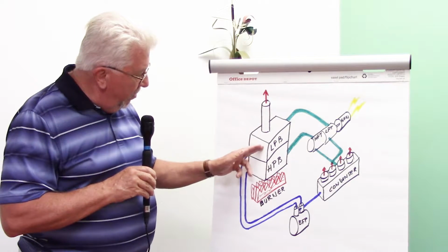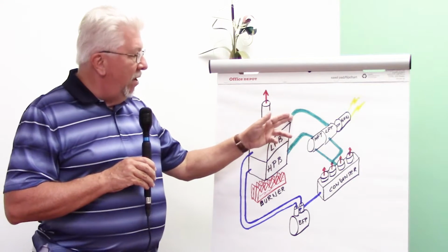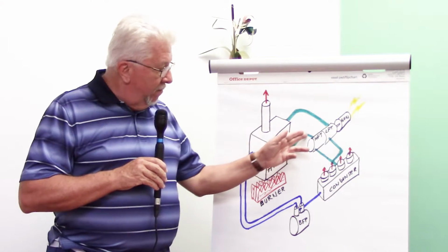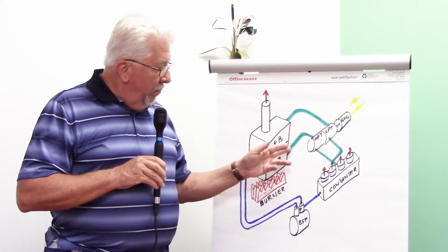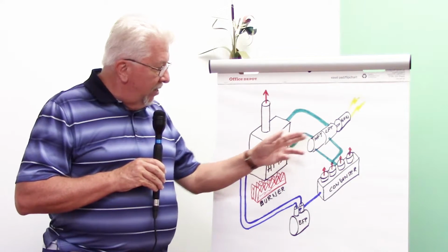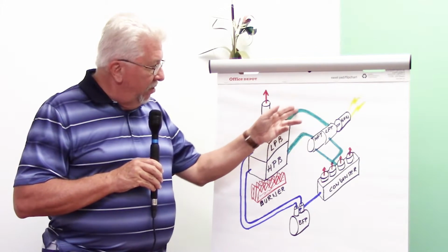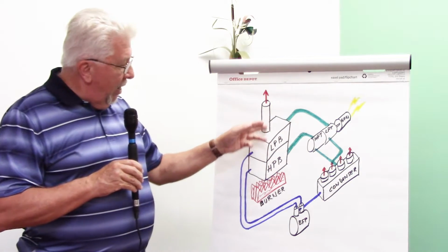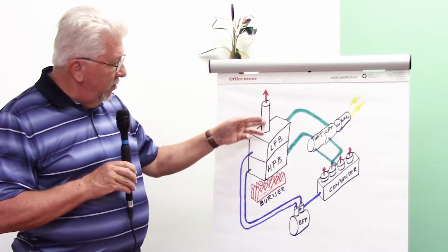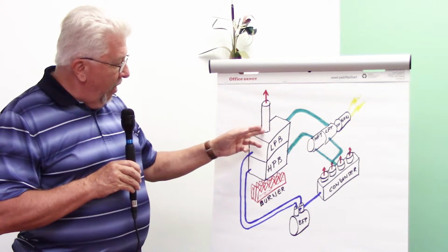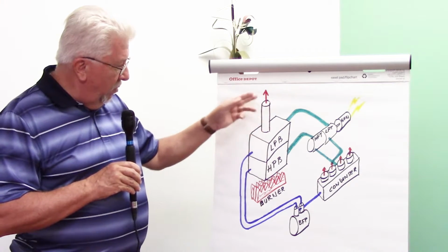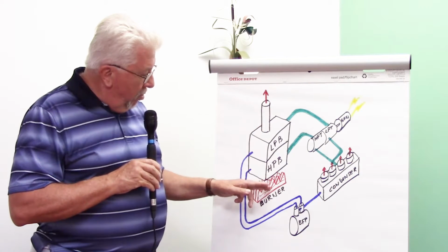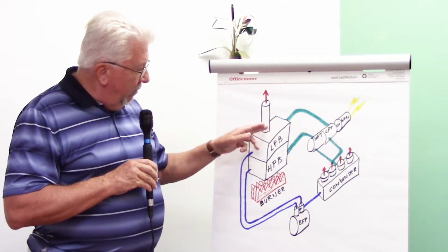They take the water in these boiler tubes, and they make steam that's around 600 degrees Fahrenheit and around 600 psi. So here you have steam that's around 1,100 degrees Fahrenheit and around 1,000 psi, and here you have steam that's around 600 degrees Fahrenheit and around 600 psi. And as it comes out of the stack, what you have is combustion products that were 2,500 degrees down here and they're 800 degrees here.